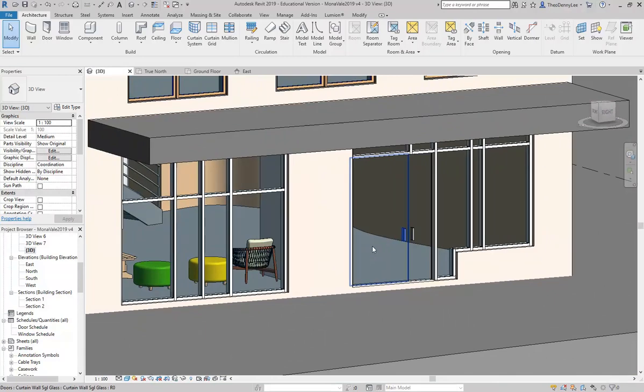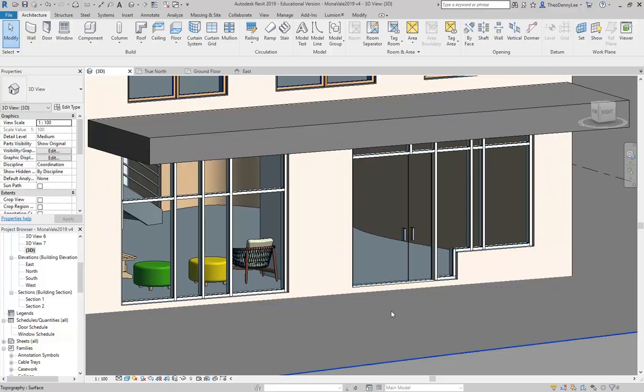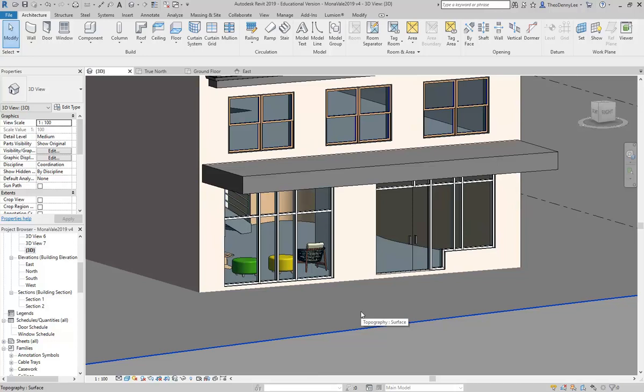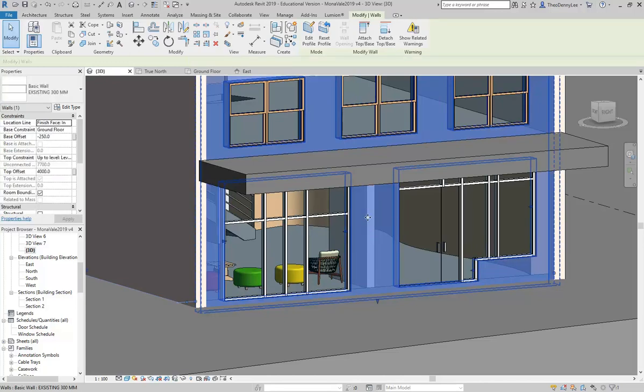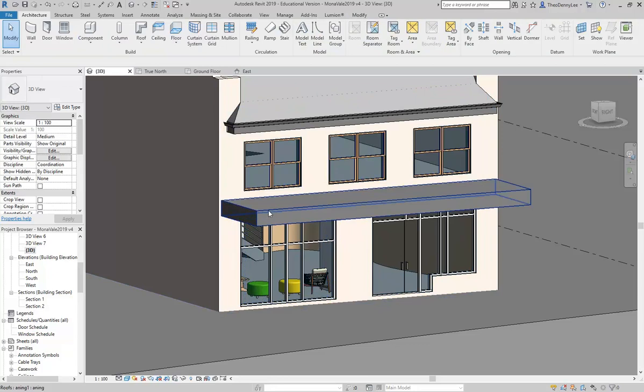And so afterwards, when we look at curtain walls, you may be able to modify those curtain walls to get the new storefront pattern that you want. Or alternatively, you can just draw a new curtain wall in the opening shapes that you've made. So that's up to you. So I'll give you some time to try making some openings or modifying your openings in that existing wall. And then we'll have a look at curtain walls, which is a bit more involved.